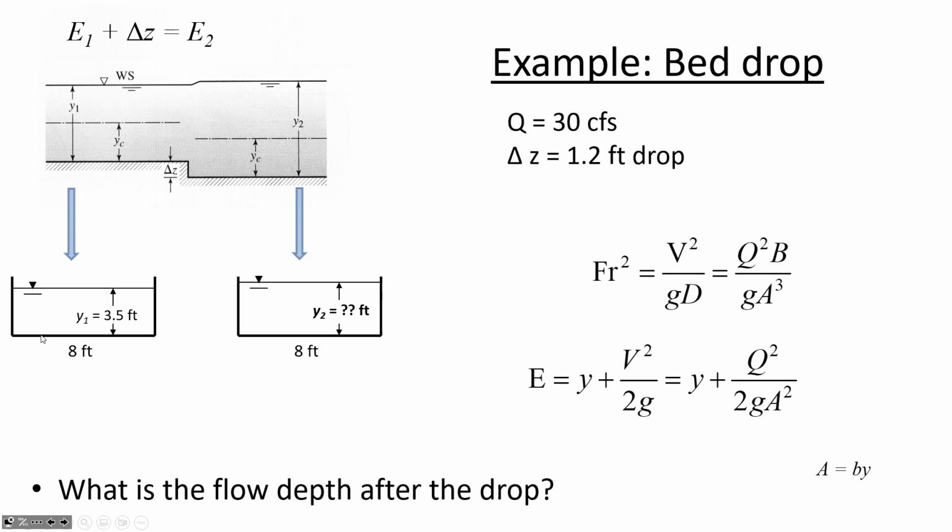So then 3.75 feet squared per second, squared, divided by 32.2 feet per second squared, to the 1/3 power. So our critical depth is 0.759 feet, that is Y sub C.